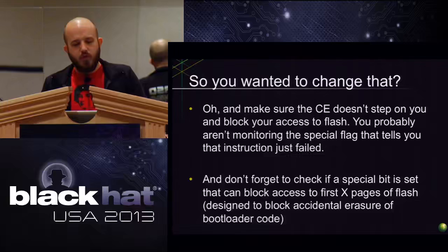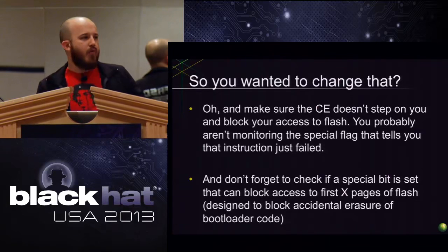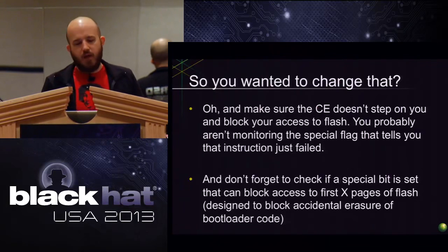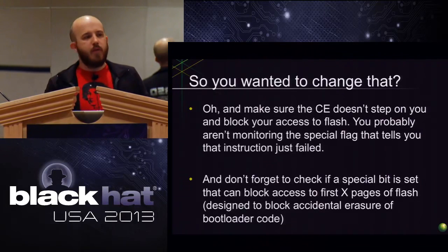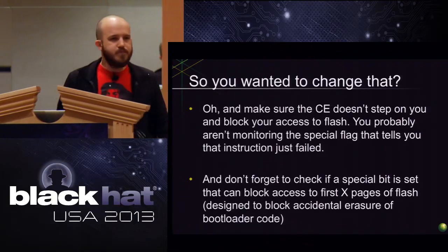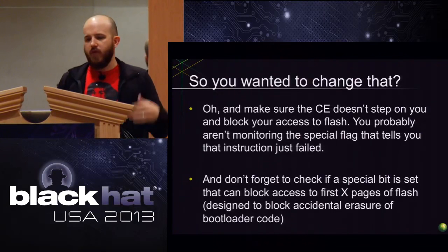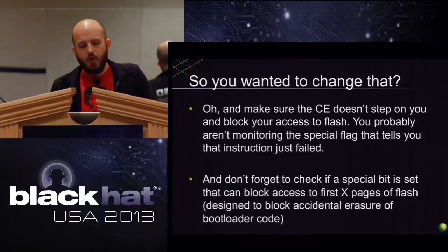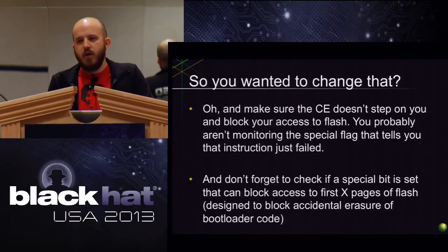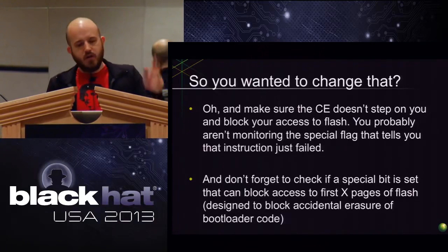It has a way for you to set certain bits that say turn off the first X pages of flash from being able to be mass overwritten. That would typically be where you would store boot code, for example. Something like a fail-safe, or the code that loads everything else. So you put that there, and you never want it to be overwritten. But it's just a bit, so there's not a security feature to that. You can just go in and change it if you need to.